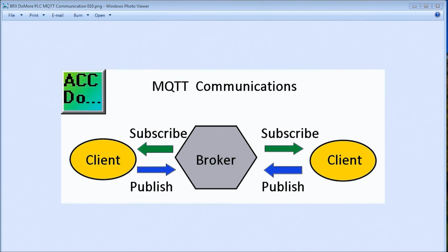This protocol provides machine-to-machine connectivity, which is ideal for the Internet of Things. This protocol is not for remote I/O or real-time deterministic applications. MQTT is a good solution for applications that move data from hundreds or thousands of machines, which have sensors, etc., to clients in many networks.